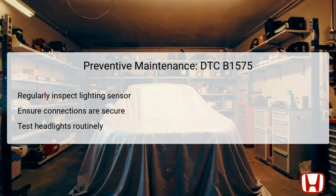To prevent future occurrences of DTC B1575, routine maintenance is essential. Regular inspections of the automatic lighting sensor can catch potential issues before they lead to code triggers. Make it a habit to ensure that all wiring and connections, especially between the sensor and the driver's under-dash fuse relay box, are in good condition and securely connected.